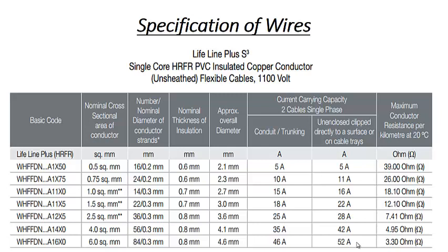This is very important because based on this data we can see which wire we have to use in our day-to-day life or in our housing wiring diagram or room wiring diagram. So usually in a normal house, 6 square mm is sufficient, because you can see this 46 into 230 comes out to be 10.5 kilowatt. So if a house or a home has a 10 kilowatt load, 46 amperes will suffice. That means 6 square mm will suffice. That's why for this case I have only mentioned up to 6 square mm.